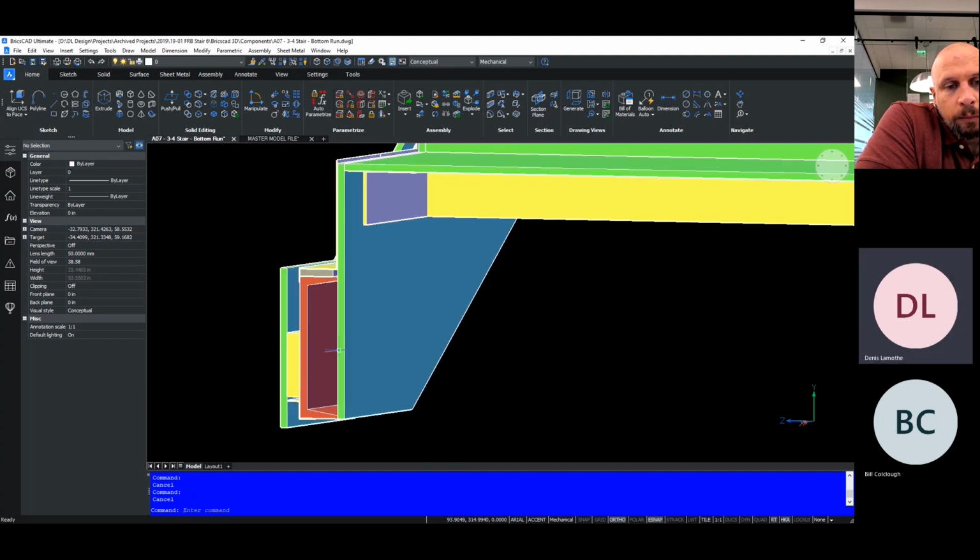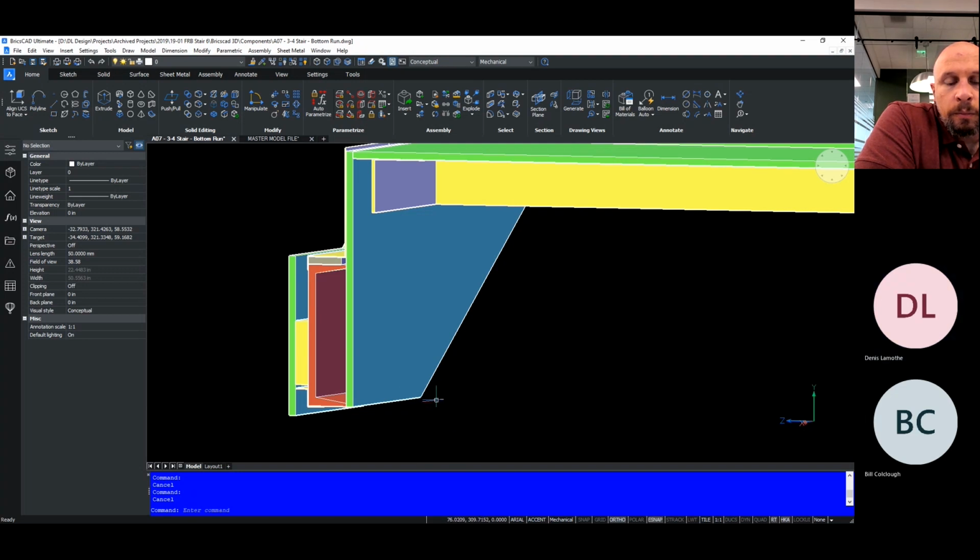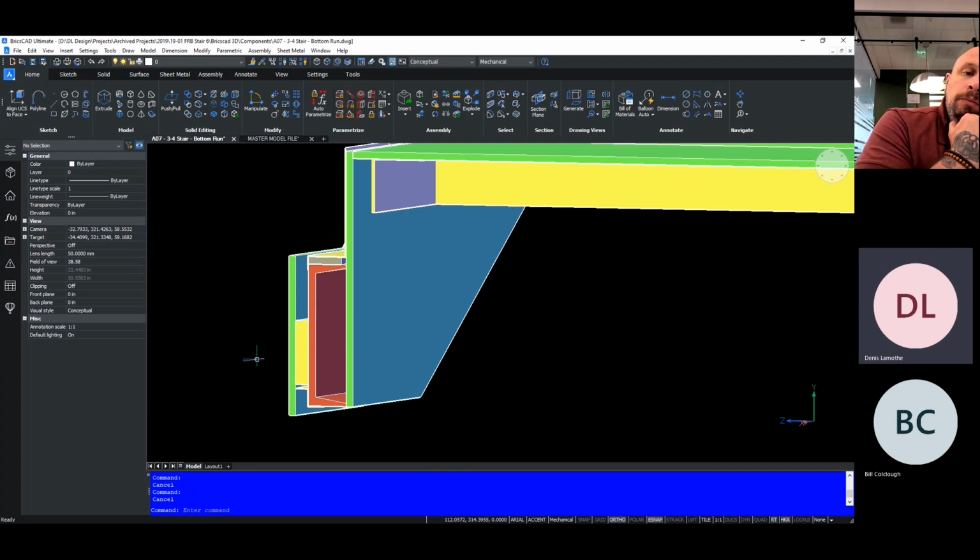It's a series of built-up parts, whether it's a combination of HSS tubing with plates or channels with plates. Sometimes the built-up stringers are made straight from 4 different plates welded together to create a box. We may do that if we can't find a stock or typical shape HSS profile, and the engineer is specific that we need a certain thickness of vertical plate, or maybe there are some other things to consider in the design overall.